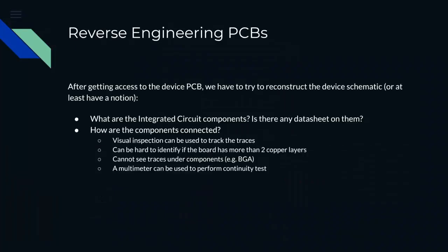So inside the board you have connections itself. If you have a BGA component, you cannot see under it. Then usually, when you have a case like this, where I think this is connected here, you can use a continuity test with a multimeter.